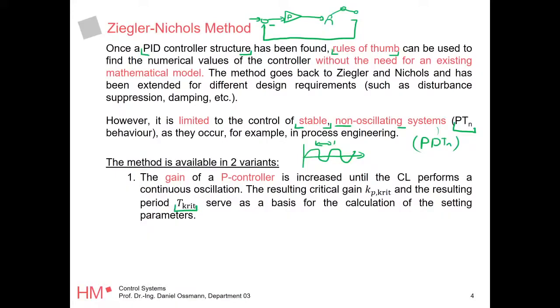And all you need is these two values. You take these two values, and from that you calculate your controller gain. And this works for P, PID, PD, whatever you like, right? You only need these two. But you see, every system will become unstable differently. So it's really hard to get, only from these two parameters, a good controller for all the systems we have, like for an espresso machine, an aircraft, whatever, right? So it's a very rough controller, let's say.